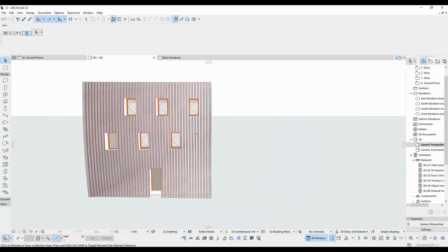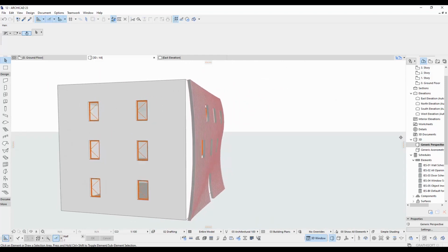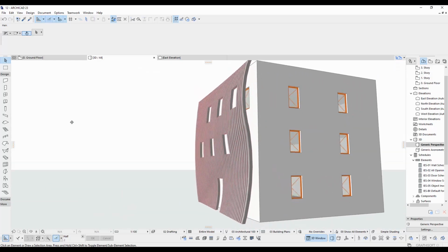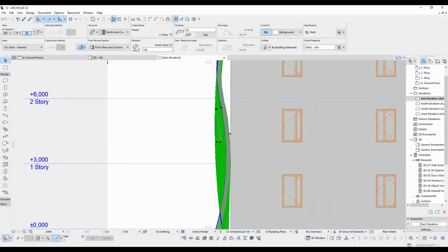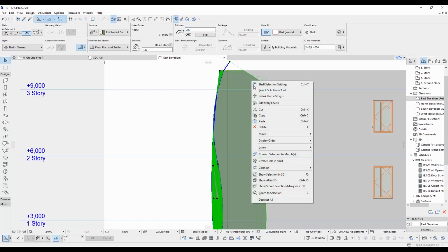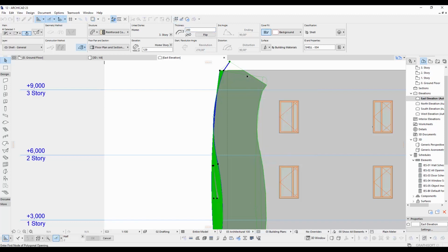Now I'm gonna close the outermost edge spaces. It is a similar way to before. I'm just gonna thicken our facade and make an opening from the side. I go to the elevation and click the shell and change its thickness to 200. Then right click it and click the hole. Now I can draw the shape that will be deleted.